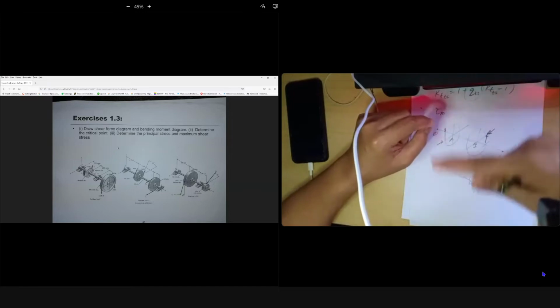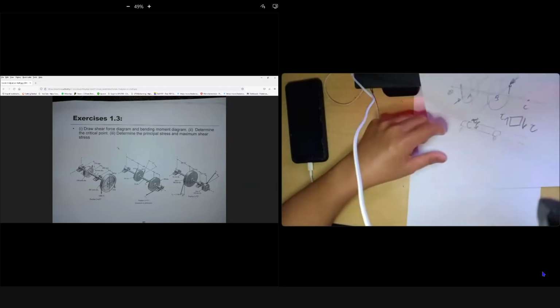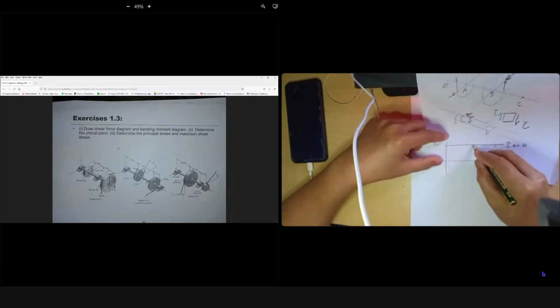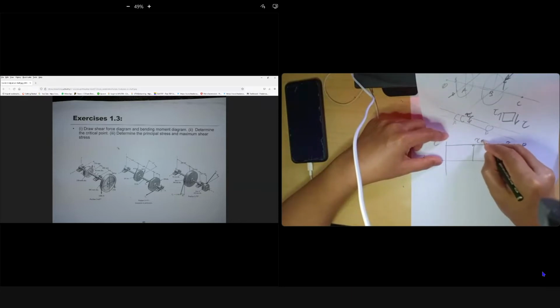The torsional stress is constant with time while the shaft rotates. So if it remains constant, your torque amplitude is 0. If you had a sine wave, we would have amplitude, but this is a constant line. We don't have alternate, the amplitude is 0, but we only have mean. Yes, the mean must be there.